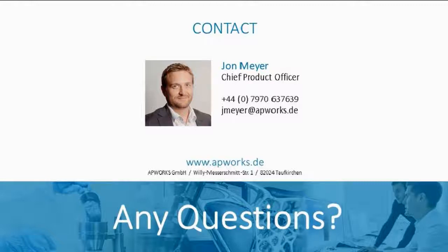Okay, thanks. Then we've got a question whether you can actually color parts with blended powders? Because in the presentation, I think it only had the raw material colors. To be honest with you, we've never tried it. My guess would be the best approach to color these parts is anodizing, oxidation colors basically, which you can do typically with things like titanium alloys, aluminium alloys.